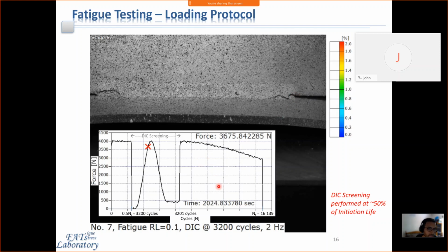So did you see crack initiation on the base material itself for any of the cases? Not yet. No. So everything was for this 590. Everything, the weld failed. Correct. None of the base material. I do have some supplemental slides. We can look at a few different failures if you like, but as of right now, the weld is what is failing. The way it's failing, eventually, the initiation always happens in the weld so far.